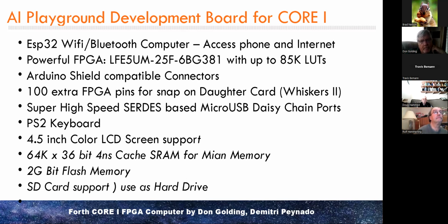The reason why I bring that up is that a lot of the classic Arduino Uno shields are 5 volts, because the AVR processor used by the original Arduino Uno has 5 volt logic. But since then, much of the rest of the world has moved to 3.3 volt or even 1.8 volt.